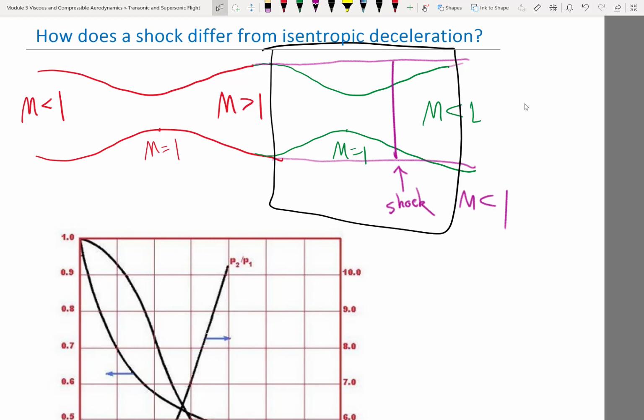It's the same, right? The ratio is equal to 1. No, there's no viscous forces, right? So the stagnation pressure, even for compressible flows, should be exactly the same. So that's our generalization of Bernoulli. I think we worked on it during the third week or something in our homework, right?